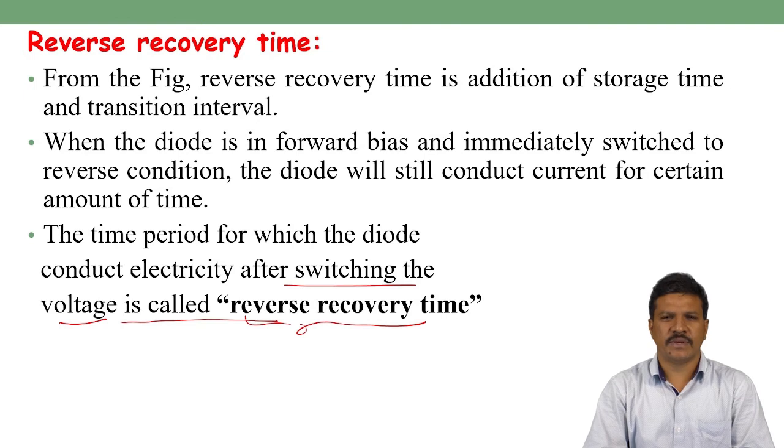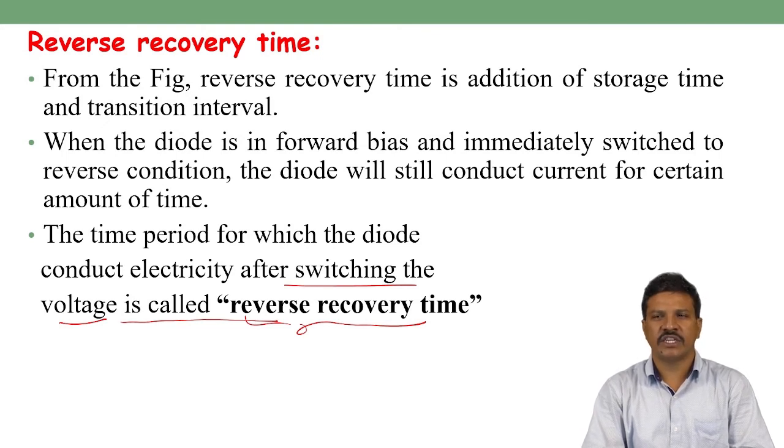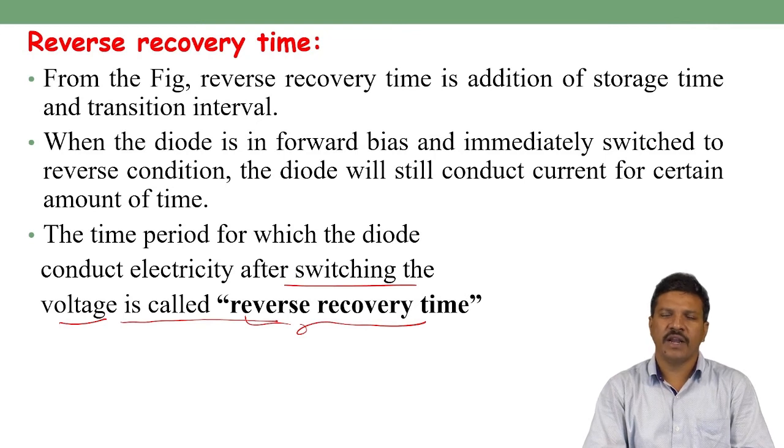This is most important when we operate diodes in logic gates. When we consider the logic gate timing diagram, every transition between on and off, logic 0 to logic 1 and logic 1 to logic 0, will always face a problem with this reverse recovery time.